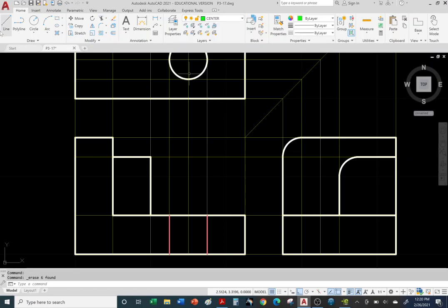We're going to use the line command. Again, you can also type in L in the command line. Type in L, enter. So just to guarantee I'm following the center of the hole, I'll start here from the top view and go straight down. Okay, so I want to extend beyond and make sure you have ortho on, right? You don't want to go off a little bit at a slight angle from the vertical.